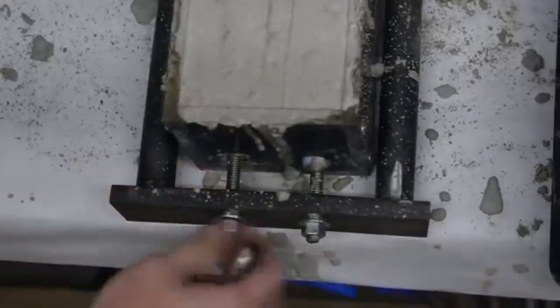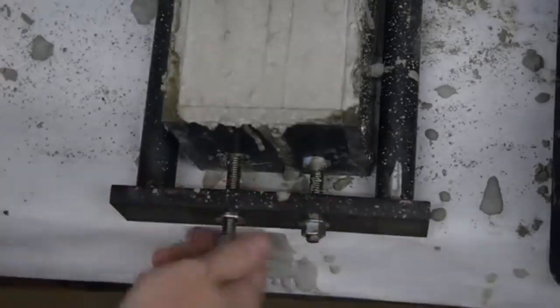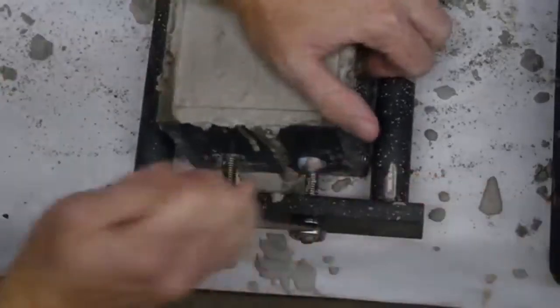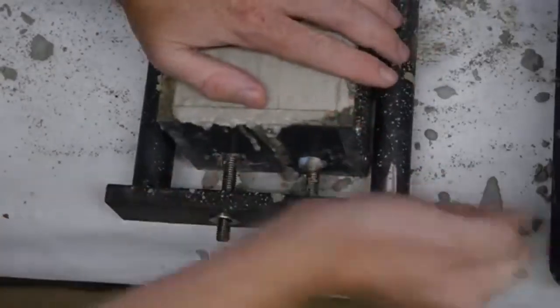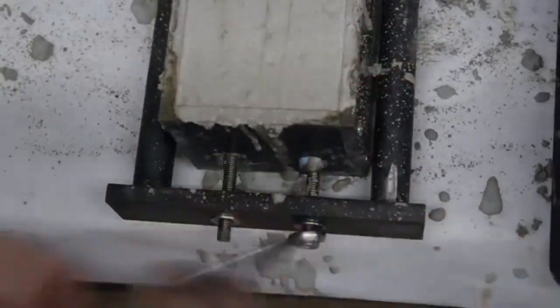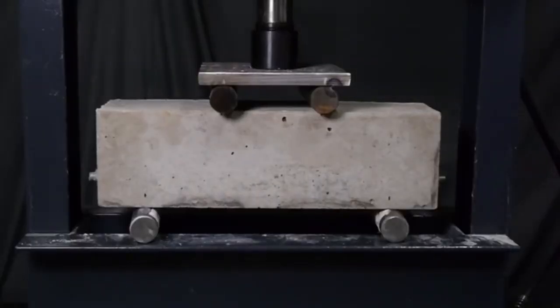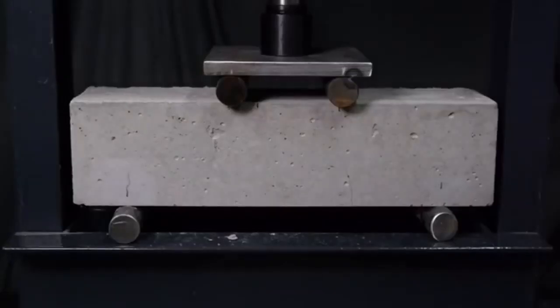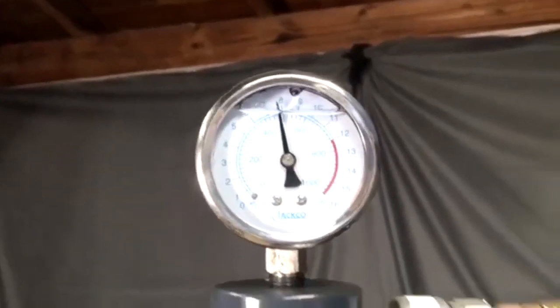After the concrete's had some time to cure, it's time to test the beams out. On the pre-tension beam, I can unscrew the nuts and take off this frame. Because the concrete hardened around the bolts, the steel rods are still under tension inside the beam. I put it under the hydraulic press for testing, and the results are easy to see. In a conventionally reinforced beam where the steel is simply cast into the concrete without any tension, cracks start forming at around 4 tons. In the pre-tension beam, the cracks didn't appear until double that force, at around 8 tons.